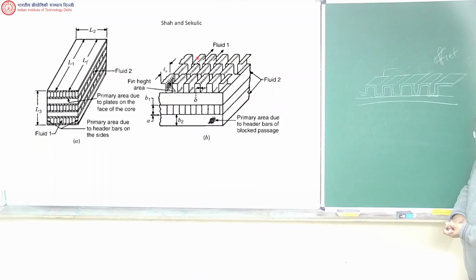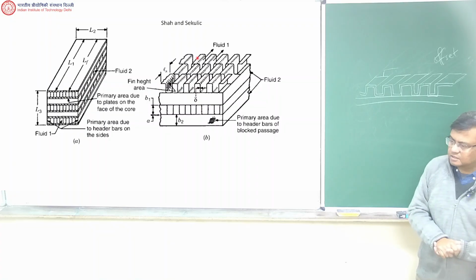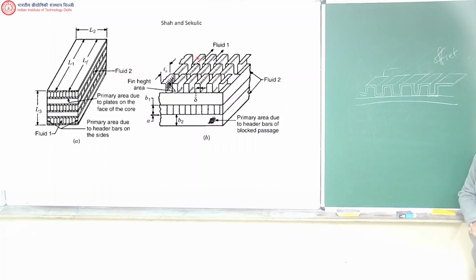So that's better usually, right? When it comes to heat transfer, this sort of disruptions, these are better. Just physically, without doing any equations, these are better. Why? Because you make the flow more turbulent and there will be better mixing. So the transport processes will be more effective and you get better heat transfer.